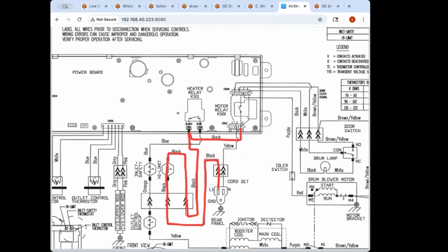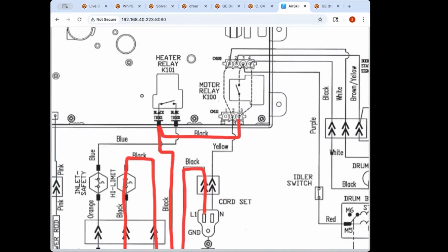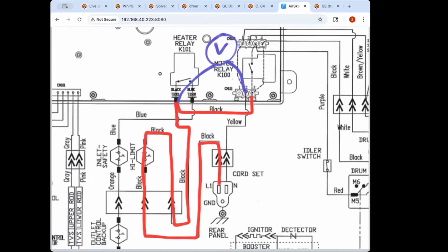And you're checking the voltage with one of your probes on one of the red lines that you mentioned. Your other probe will be on CN11 pin 2. Yep. And then over here, is that neutral? Yep. Okay. Yeah, I can draw in neutral to make that clear.